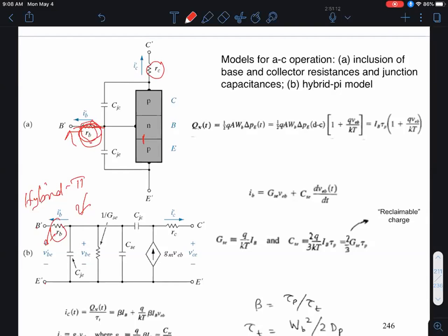While I'm on this slide, I'm also showing this parasitic series resistance of the collector, and you don't want that to be large also. Okay. However, you're kind of in a bind because this collector base junction is generally reverse biased. Therefore, that forces you to make your collector doping low, so that the reverse bias breakdown voltage is high. And that, of course, would increase the RC, which you don't want, okay? So you want to kind of have your cake and eat it too.